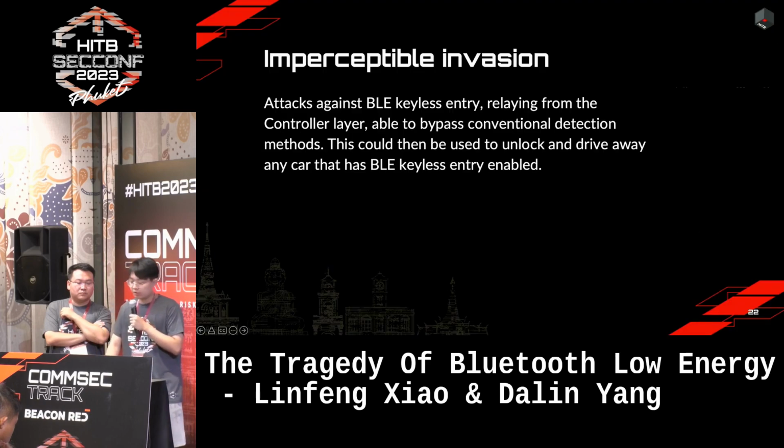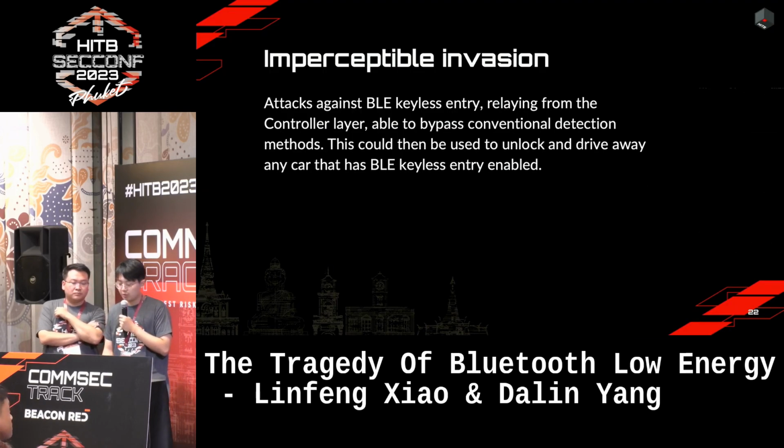Okay. In the third part, I will introduce BLE controller relay. The relay attack is a security risk caused by the modern keyless entry system. Before 2016, some BLE-based relay tools like GATTacker had been publicly disclosed, which perform attacks by emulating the GAP layer in the BLE protocol stack. And relay attackers can use multiple relay devices to forward signals from the legitimate initiator to the target device, bypassing physical distance restrictions.